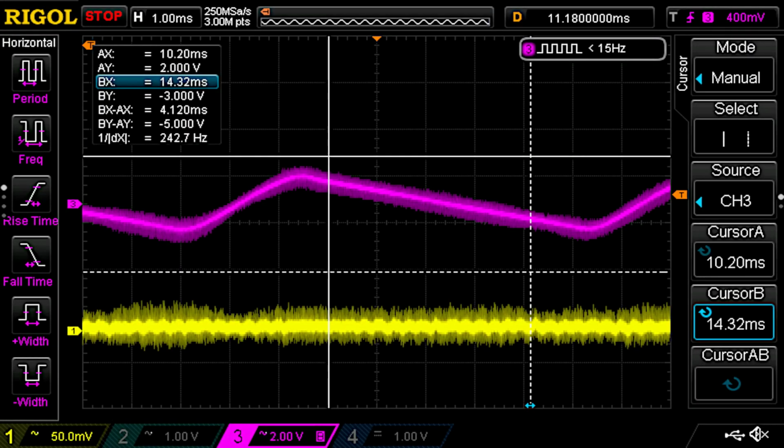And again, it's not in the voltage waveform. Makes me wonder if it's really there or some interference the scope probe is picking up. It looks to be around 2 kHz. And if it was really there, I don't see why it wouldn't show up in the voltage waveform. As we've seen, it can drive the power supply at 45 kHz, so no reason 2 kHz wouldn't show up.